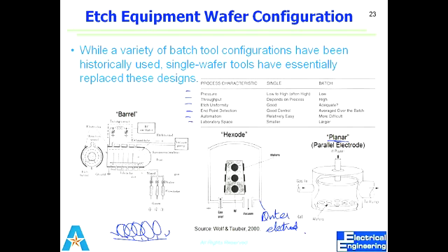For example, if I am using optical emission spectroscopy on a single wafer, I can exactly find out this is the endpoint. It will be more accurate, because the scattered components or wavelengths are from a single wafer. But if you have a batch of 25 wafers, the etchant signal goes up, but it won't be as accurate or give as good control of calibration, because maybe most of the wafers have reached their endpoint, but one wafer, due to some non-uniformity, has not. Collectively, the signal will go up. That's why there is better control, and we will have more reliable data in the single wafer case.